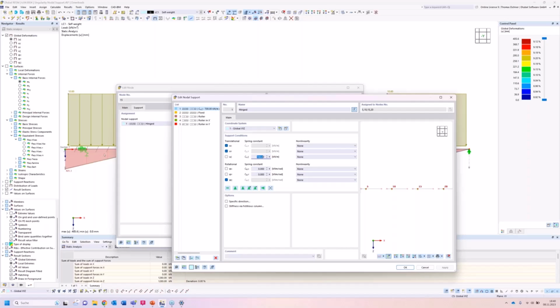For bigger systems where you have walls, and especially if you have a combined system of columns and walls, and you have modeled your columns as fixed, then you will have lots of singularities. So in practice, for especially reinforced concrete, for mid-size models, you would create two models.